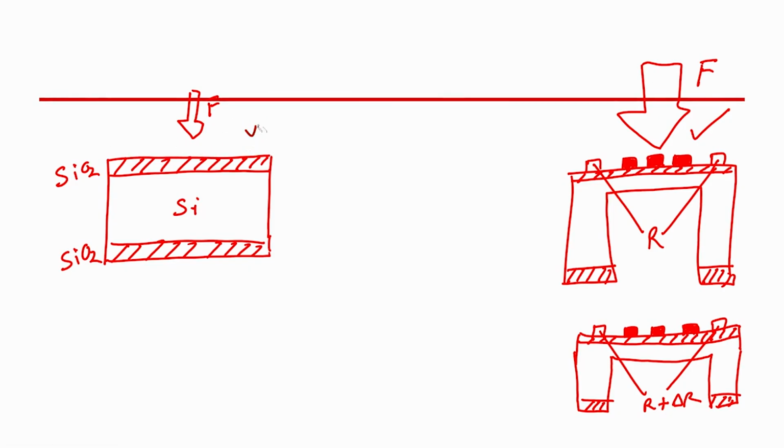See, you take an oxidized silicon wafer, and then coat a material that is used for your strain gauge. So, this is your material for strain gauge. Next step is, you will spin coat, what? Photoresist, right. So, you will spin coat positive photoresist. Okay. Then the next step would be soft bake.